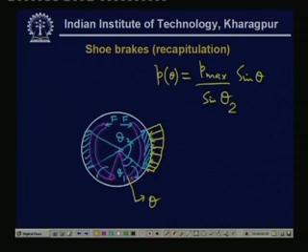Now, it of course depends on P max. For different friction materials, the P max is limited. So, once we know this P max, we can find out the maximum P theta. P theta is known because P max is now known, so this distribution is entirely known. From this we can find out what will be the value of F.